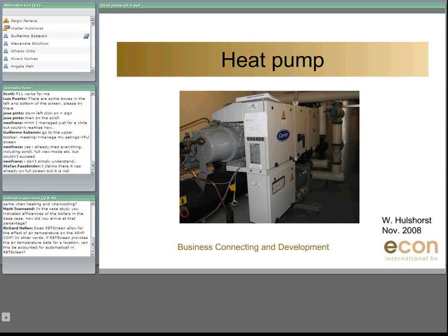Yes, if you have a ground soil system, I think that's no problem with that, because the ground soil can be used for heating and also you can use it for cooling. The large temperature difference will give you less performance. So my opinion is to use it. There's also an opportunity because the ground soil has a higher range, which is also better compared to the air source. Very good, thank you, Walter.